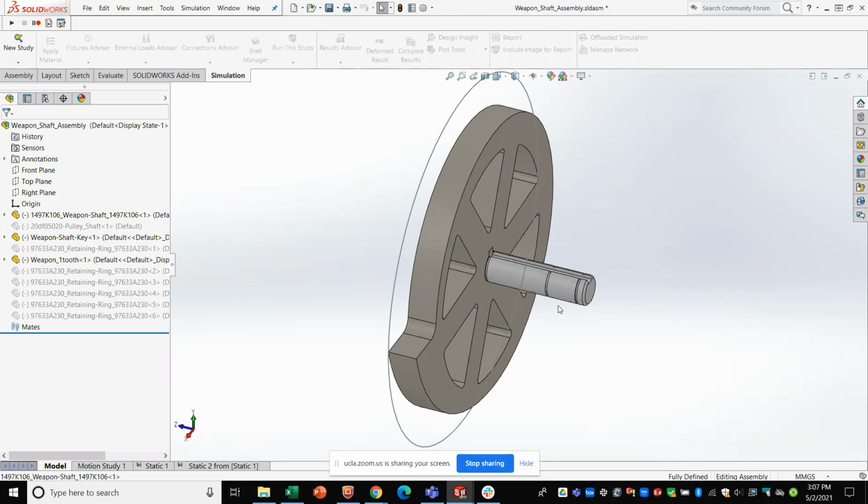Yeah. I can't give you a general rule, but I can say that you use bonded when you want the parts to behave as a solid object together, and when you expect them to behave as a solid object together. And when you expect or don't care that they can transmit forces in all directions. So that includes shear, pressure or compression, tension, twisting, basically all of the things associated with a solid object is when you can safely use bonded contact.